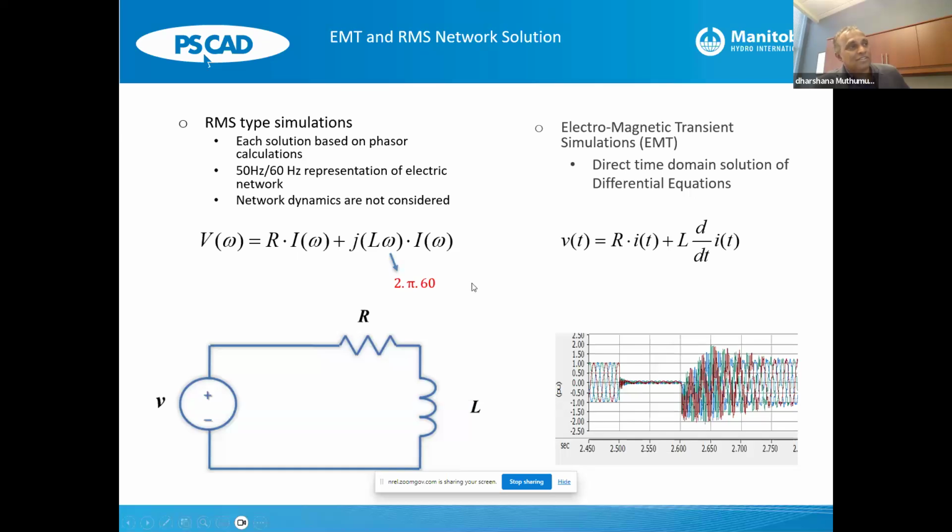Unfortunately, inverters, unlike synchronous machines, can perform poorly in the presence of significant or nasty network transients of this nature. So that's really what is driving the need to perform EMT studies to get accurate responses of inverter-based devices. The impact of network transients on the inverter is not accurately or fully captured if you